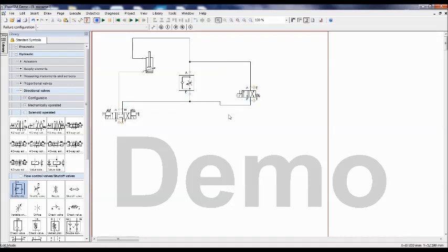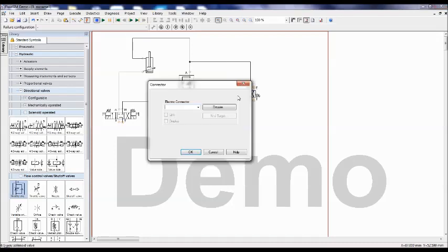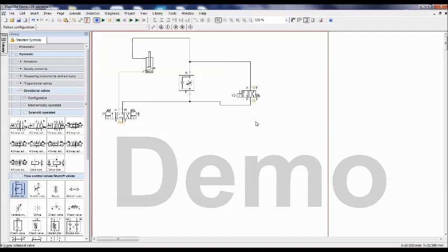That means, see, solenoid Y3 by default is off. So if solenoid Y3 is off, what happens? There is no flow from P to A, right? That means blocked position. So oil has to flow through the throttle valve. So that is a restricted flow.